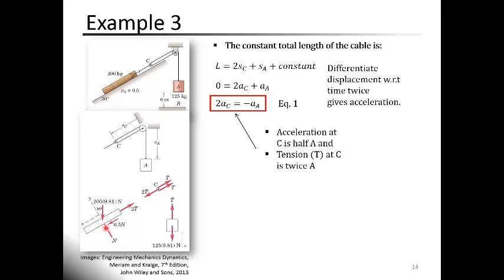Okay. So we have another force here, which is the weight of the log, because the log weighs 200 kilograms. If you multiply this by 9.81, we get 200 multiplied by 9.81 Newton. The italic symbol N is a force, and this one is Newton. We have an angle of 30 degrees between the vertical weight component here and the y direction. So this is the positive y direction, this is the negative y, and this is the positive x direction. So positive x direction along the ramp, positive y direction perpendicular to the ramp.